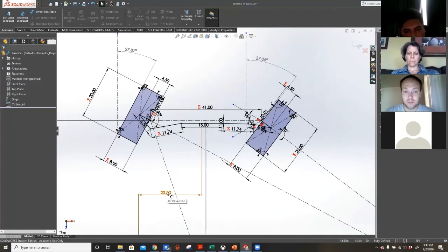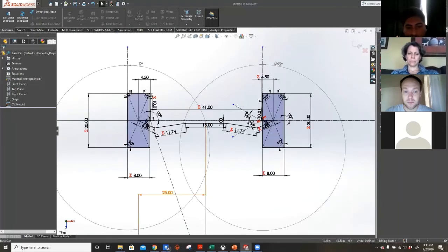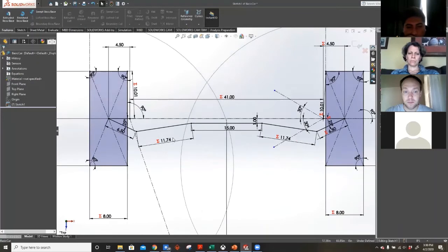All right, well, you guys are getting close, but I would always err on going slightly excessive Ackerman because it's going to give you a better turn radius to meet in the front a little bit. So I'd go even more excessive Ackerman. Go make it 25 again because you're still meeting behind the wheels, right? So yeah, move that to like 20.